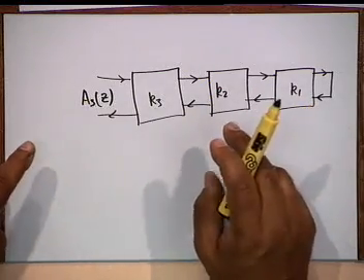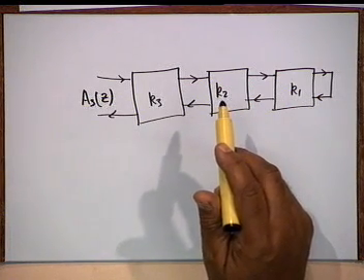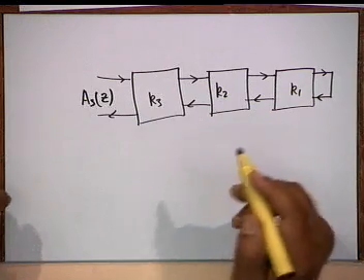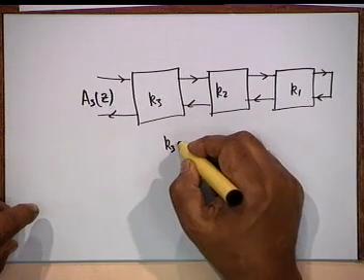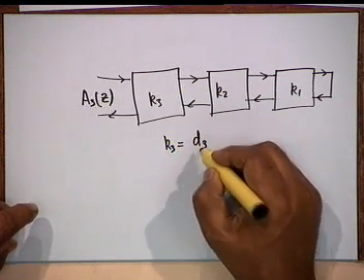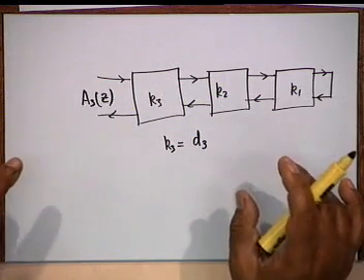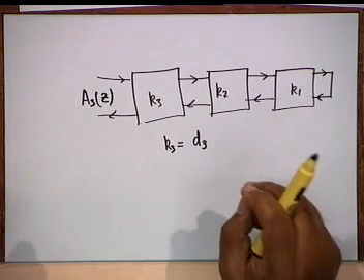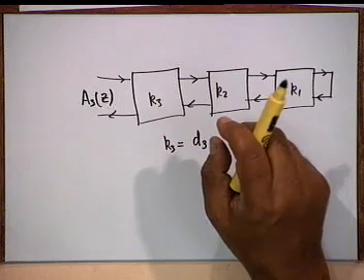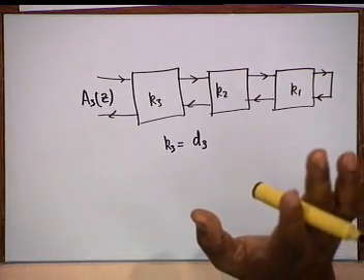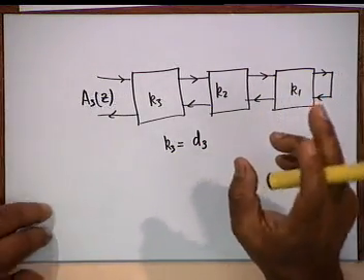How? By using that relationship, that is di prime equal to di minus dm times dm minus i, divided by 1 minus dm square. K3 obviously is given. K3 is the same as D3. So you have to derive K2, K1. Okay? And if in the process one of these exceeds 1 or is equal to 1, then you need not proceed further, because the structure is unstable. There is no point, you cannot realize the transfer function. Okay? We shall stop here and continue next time.